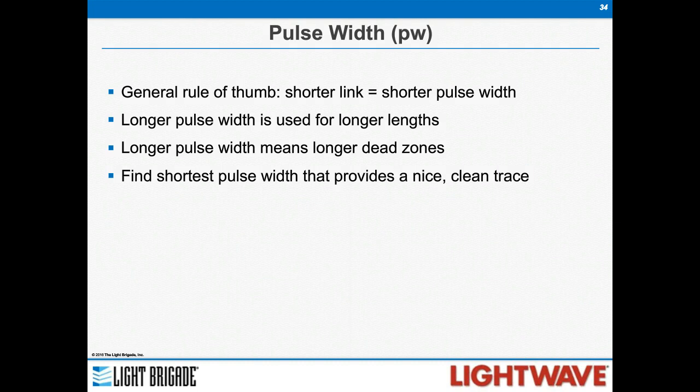We encourage anybody who's going to do OTDR testing to really get a spool of fiber or a length of cable and do some experimenting on your own, because the best way to figure this out is to see the results as you make changes. Change the pulse width and test the length, and then change it again and test it again, and take a look at that trace. Is it nice and clean, or is it really noisy? Are you seeing things clearly? Are you able to see a connector? Are you able to see the end? It'll start to really click with you what works and what doesn't.